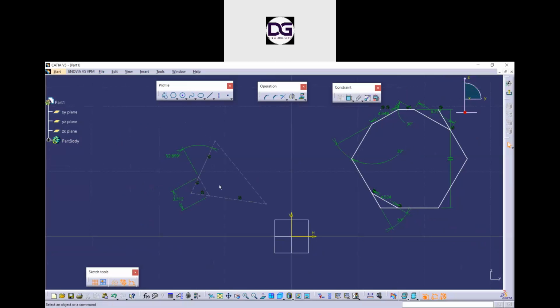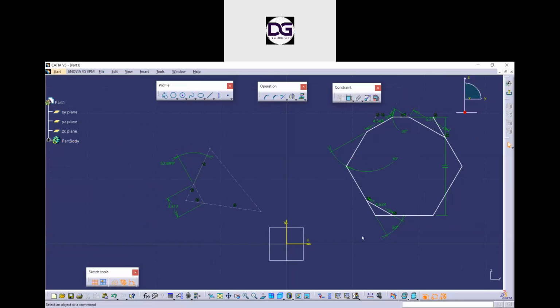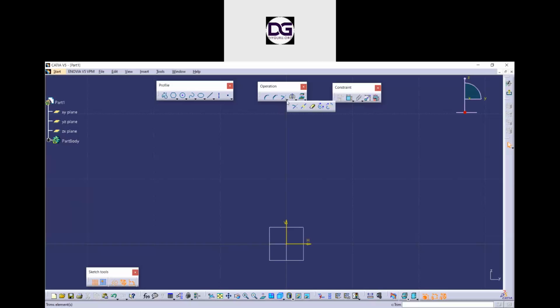So that are the generally used chamfer options that CATIA provides. Now let's look at the other options in the operations tab. The third is the relimitations tab. Here you can see that I have a drop down menu, so I will just drag this as we have learned earlier. We can drag these options out and we have the relimitations tab. In this tab we have trim, break, quick trim, close arc, and complement options. So let's see what these functions do.